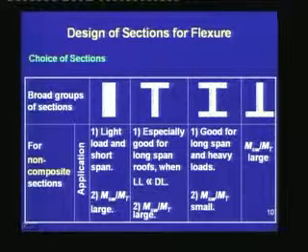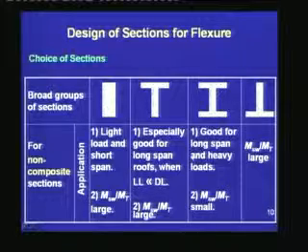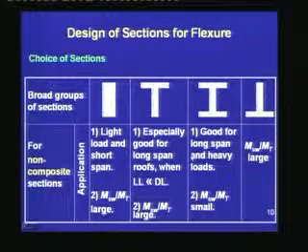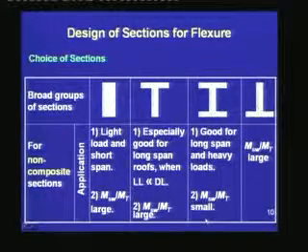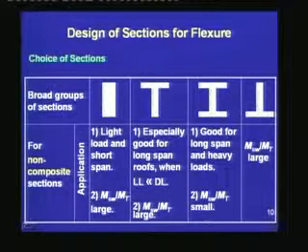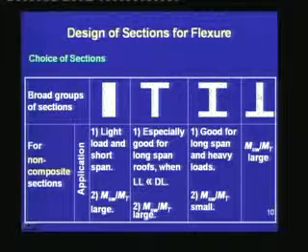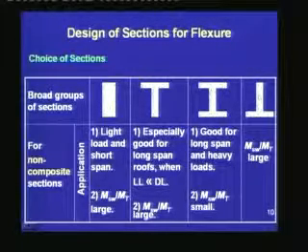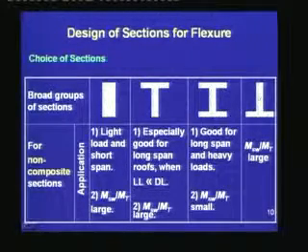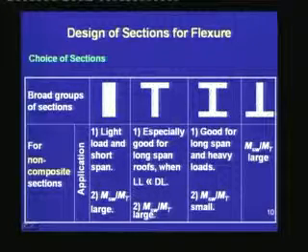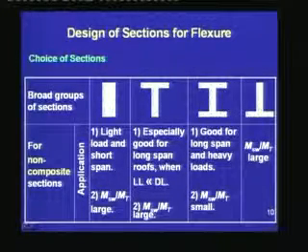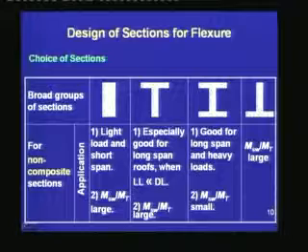For I section, they are good for long span and heavy loads. Here the MSW by MT ratio is small compared to the rectangular and the T sections. For the inverted T sections, the applications are rather limited. When we use them, the MSW by MT ratio is large.